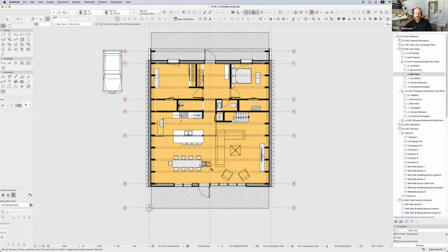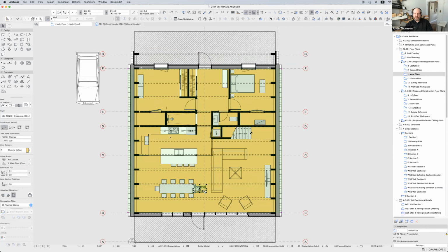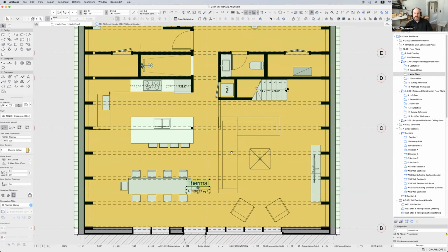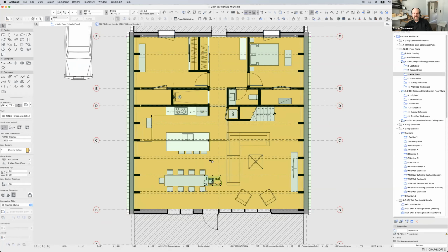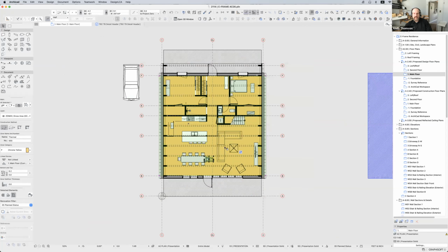So the floor plan for this one, the way I modeled it is we've just got one zone and we called it thermal. And it is like a net area zone that we then trim to the shape of the building. And the best way to do this is the automated little thing, but you can do a manually defined zone, like one where you go click, click, click, click, and create the polygon for it. That works just as well, as long as it's touching all the surfaces of the building. So what does this look like in 3D? This is basically a south-facing building, and we have fewer windows to the north, more windows to the south, and we plug this one zone in here.